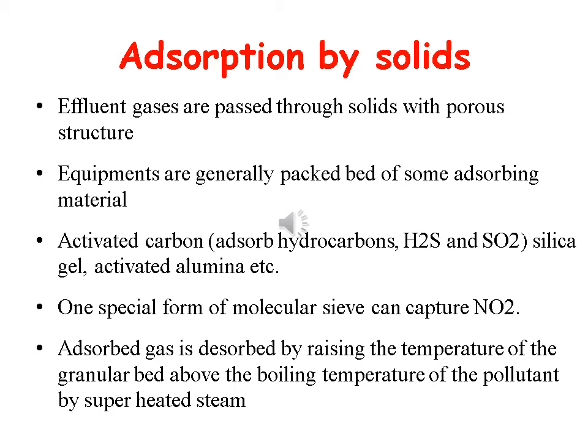Then we remove the collected material from the adsorbent by raising the temperature of the granular bed above the boiling temperature of the pollutant, or by reducing the pressure. In that way we can remove the pollutants from the adsorbent.